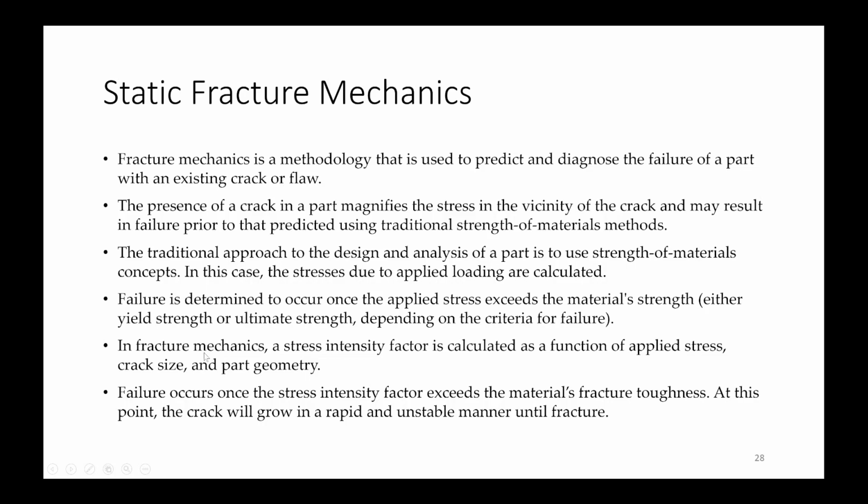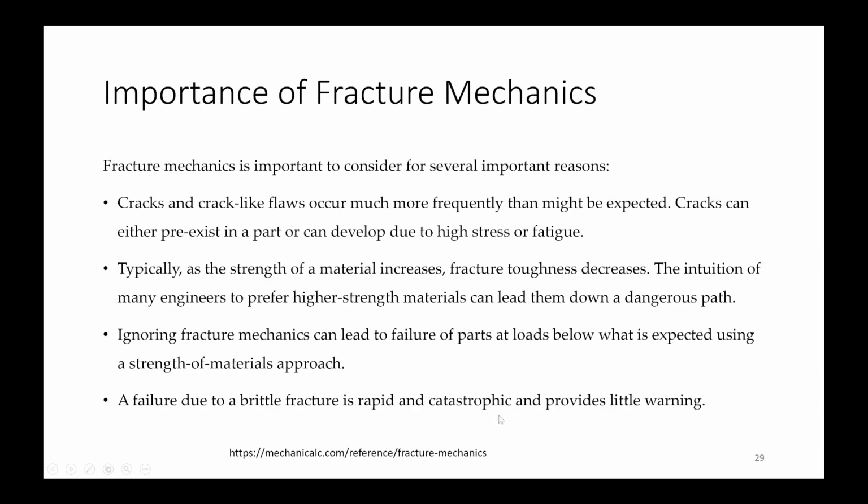While in the case of fracture mechanics, the stress intensity factor comes into play and it is calculated as a function of applied stress, crack size, and part geometry. The failure occurs once the stress intensity factor exceeds the material's fracture toughness. At this point, the crack will grow in a rapid and unstable manner until fracture.